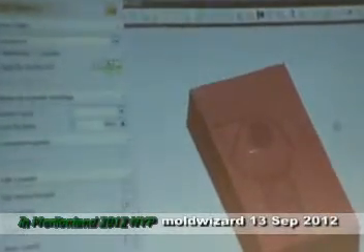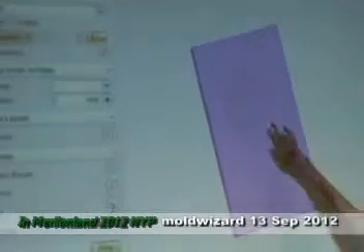So if I want to design a 2 cavity, I need to define where is the next cavity. One more cavity, right? One more product. Where's the location for the second product? So I need to decide. I need to specify the location of the second product. For example, now I want to do this. Click. Or you want to put the other one on the other side. So you reverse it.